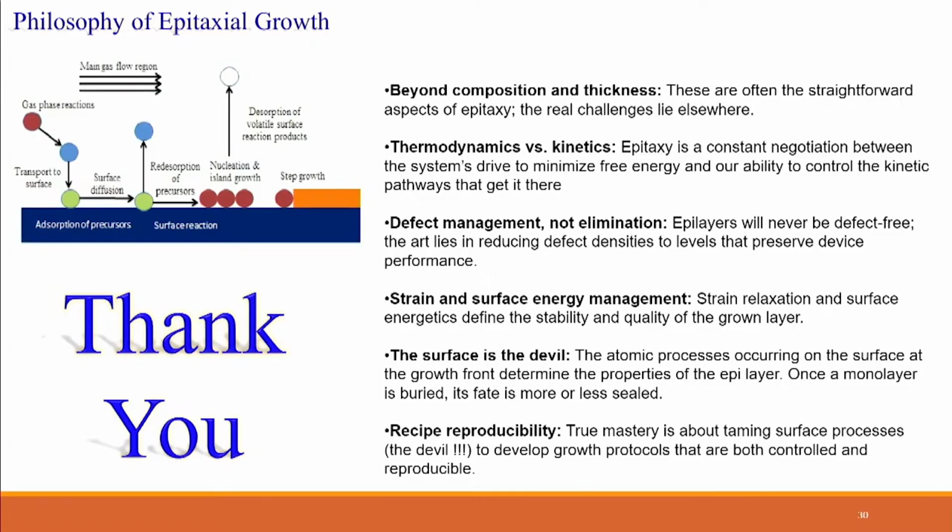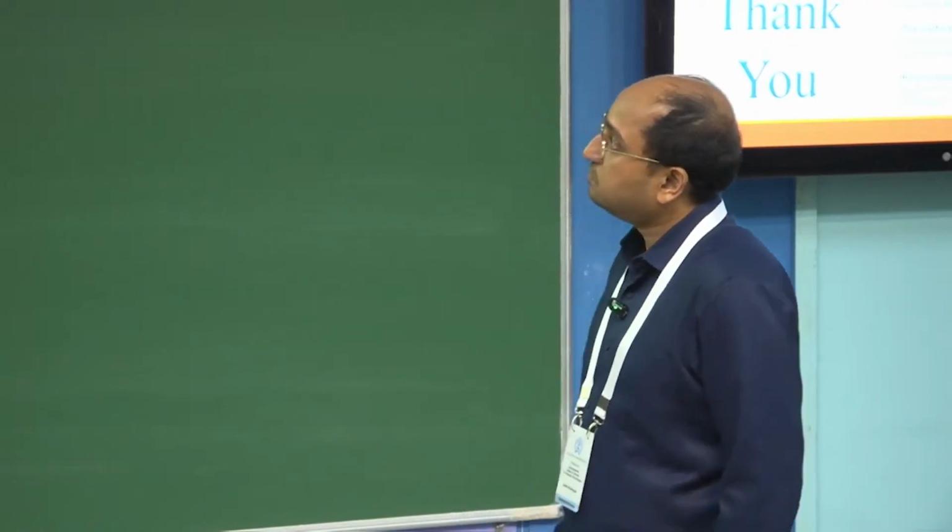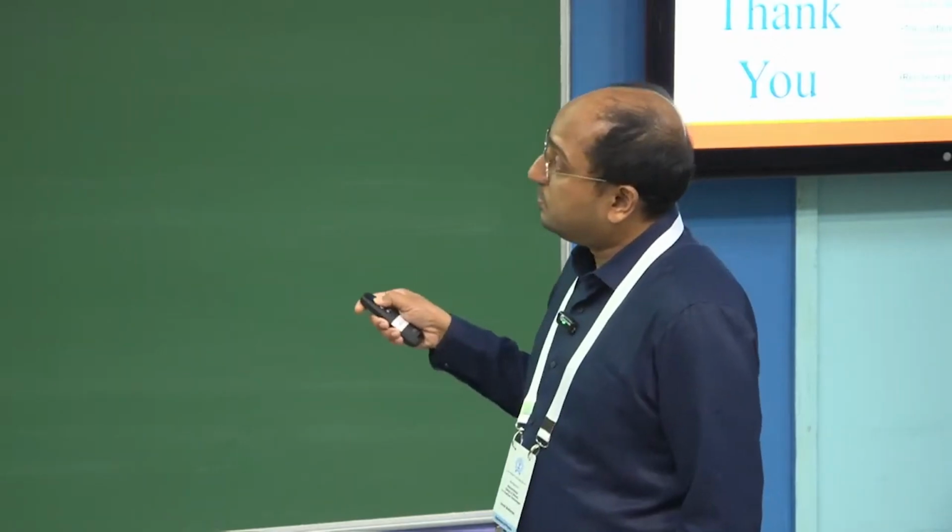In heteroepitaxy, we have to live with defects. We cannot have defect free. It just depends on the final application, what the tolerable limit of defects is and how we can manage defects. Strain and surface energy in heteroepitaxy become critical. Understanding them is the key to having more optimized layers.